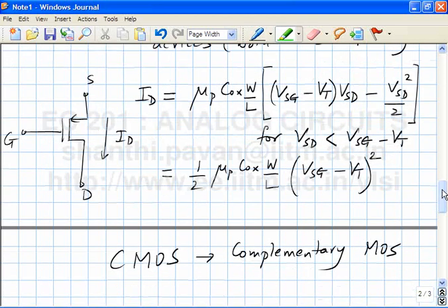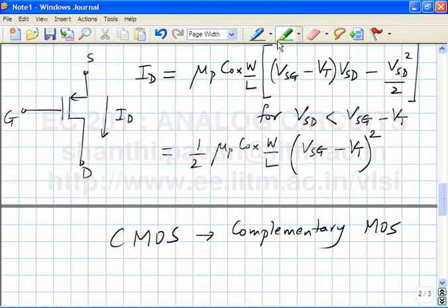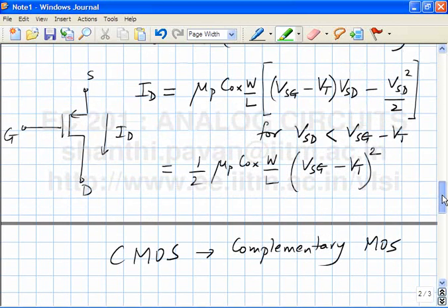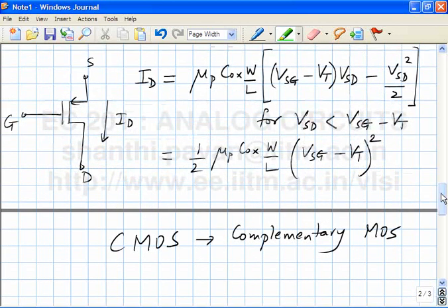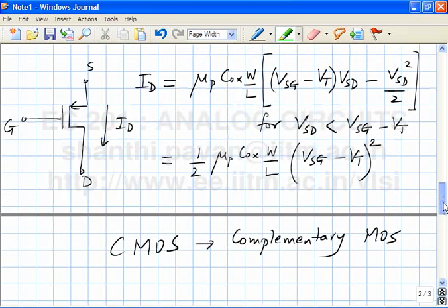So these are the device characteristics. What are we interested in next? We're trying to build amplifiers with this kind of device. So the next thing is to find the incremental gain, and everything incremental depends on the small signal properties of the nonlinear device. So what we try to figure out is what the small signal equivalent of this transistor looks like. It must look very similar to what we saw in the NMOS case. So let's just go through the motions and figure it out.